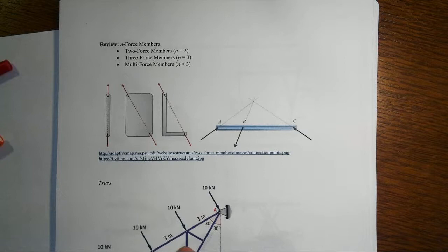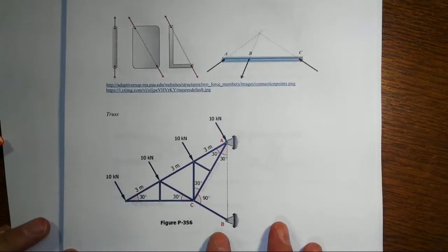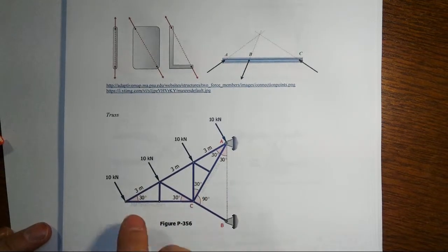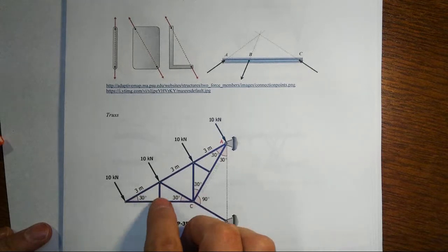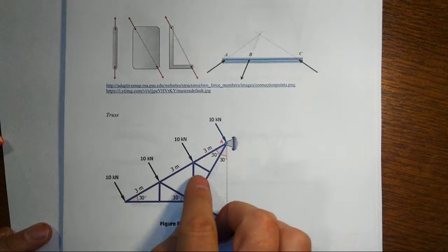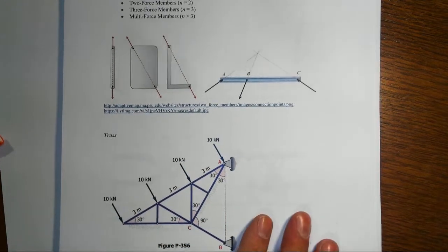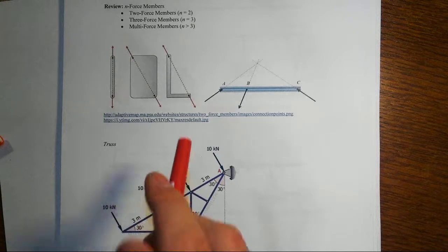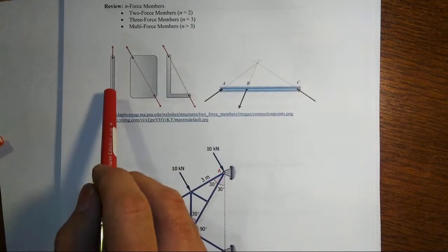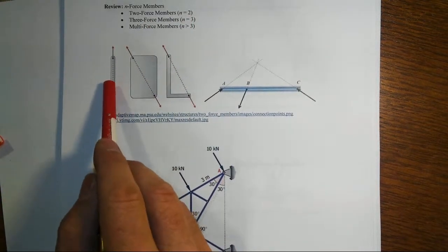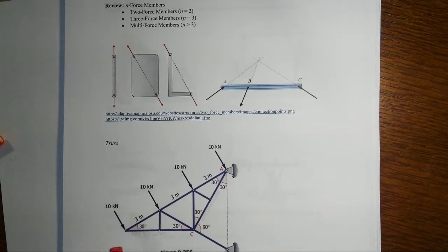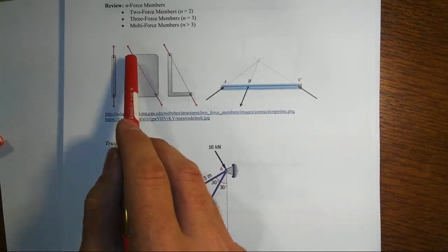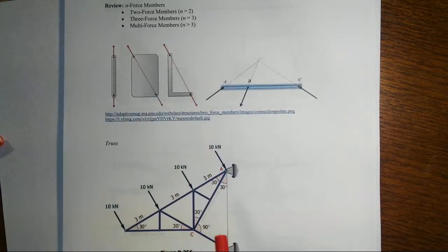With trusses, we ended up with everything being members that went from joint to joint to joint, and all the joints were pinned. And so with the loads being applied only at the joints, that meant that we ended up with a whole series of two-force members. Now, two-force members don't have to be just straight. They just are typically in trusses. They can be any sort of object that has only two pins, and that's where effectively the member gets